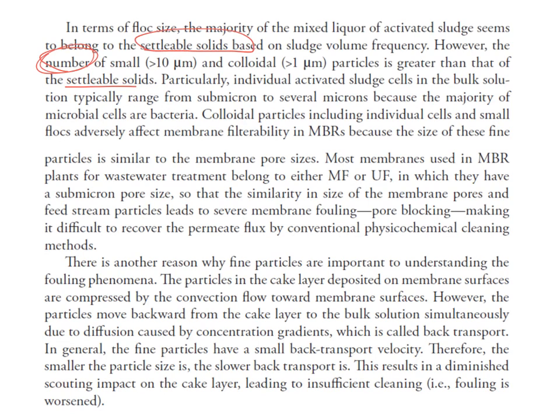Most membranes used in MBR plants belong to either microfiltration or ultrafiltration. They have a submicron pore size, and the pore size is similar to the size of the small particles in the mixed liquor.